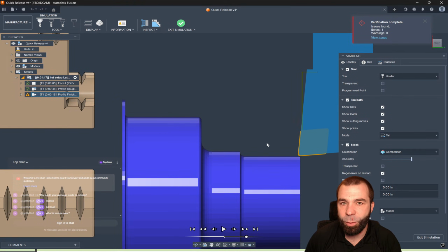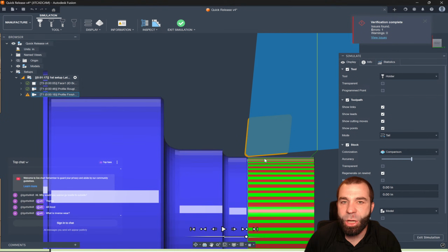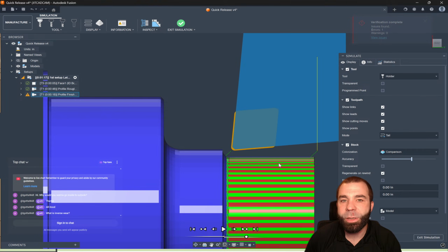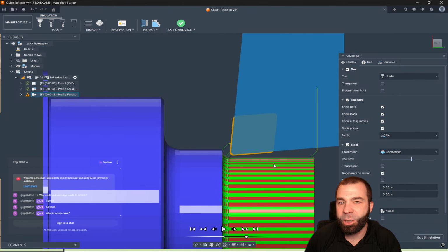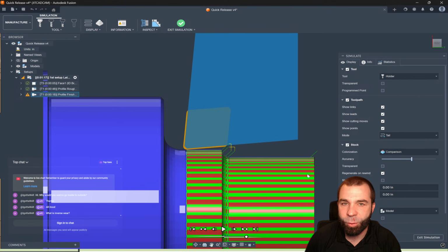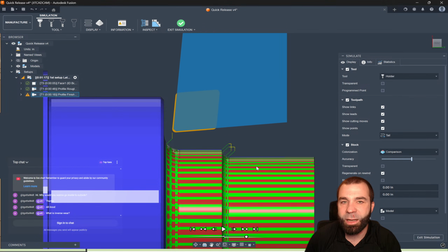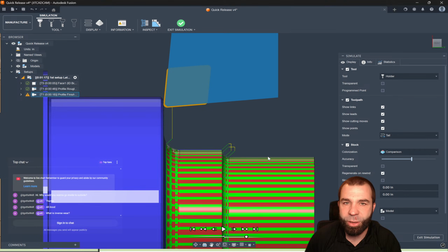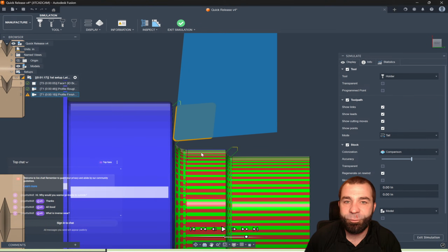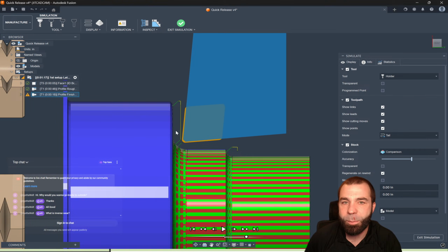So again, we're going to go in, and because we're doing no dragging, we're never going to drag this tool based on the cutter direction. As you can see there, I came down that vertical wall so that I could feed in, again, getting to a point where we're going to transition out and feed back towards center. So I'm never back dragging on this part of my insert.